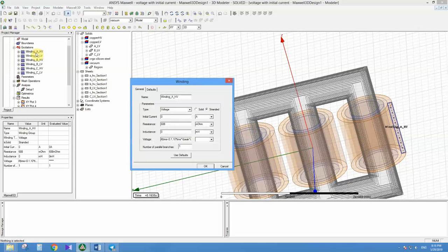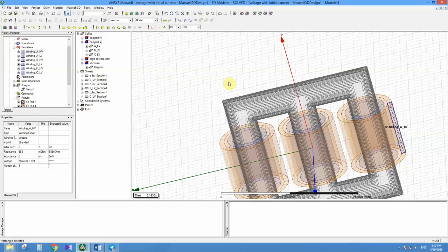When you use high voltage and low voltage excitation at the same time, the flux can't go through the cores correctly because the flux is related to the voltage. So if you want to excite the transformer, just excite one side and use the other side as a load.